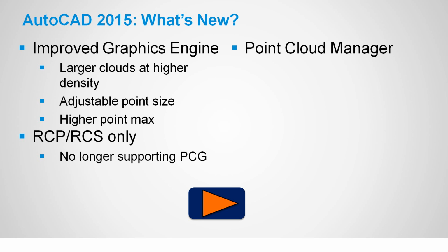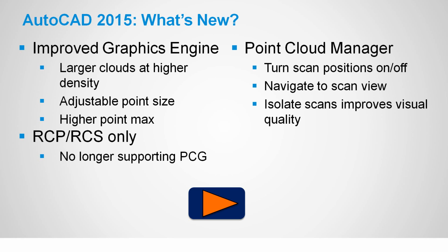As stated, there's a new point cloud manager that you can find in 2015, and this is great. You can now control per scan, turn each scan on or off, navigate to individual scan views that the scanner saw at that position, and when you isolate particular scan positions, it improves the visual quality in AutoCAD.